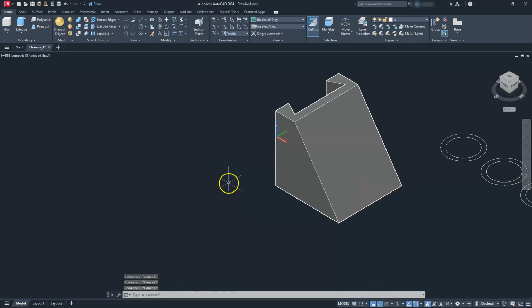I'm just going to go ahead and undo that really quick. And then the second option you have is if you want to actually move our UCS. Now moving the UCS is easy. We can select here. We're going to select the square, and then we're going to place it on this endpoint. Now we have to take note of which way is our positive X direction and which way is our positive Y direction.